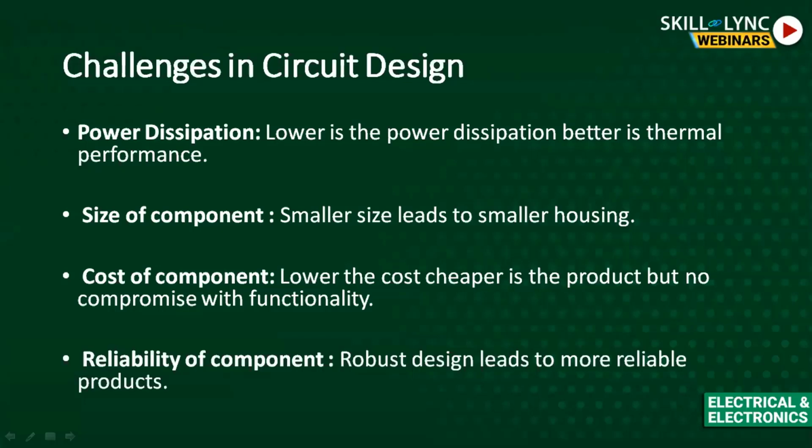And then another big challenge you see in circuit design, which is not mentioned here, is EMI EMC. This is really important: when you design a product, you need to understand in which area my product is going to operate. If there is an environment surrounded by many switching devices like antennas and so on, you will have interference from these neighboring devices to your device, and there are chances that your product could not work as expected if there are switching devices inside your product. So this is really, really important.